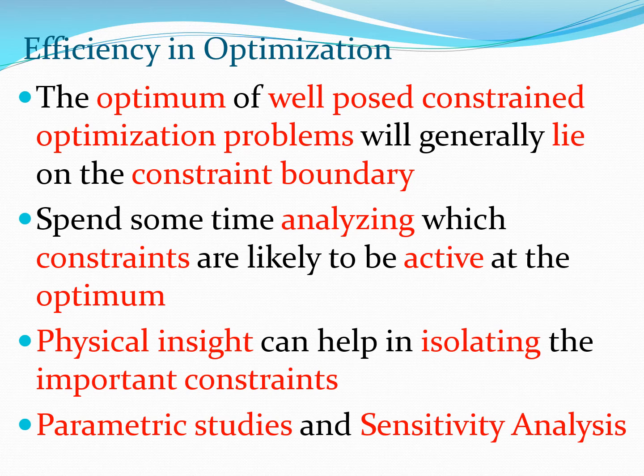So in those cases, you can do parametric studies, or there is a whole field called sensitivity derivative calculations. And these particular parametric studies and sensitivity derivatives will tell you something about which design variables are most important. Now in parametric studies, you essentially vary the value of the different design variables and see how the cost function and the constraints behave when you vary these values. So you could fix one value or a few values and you could move some of the values. So basically parametric study lets you get a picture of the system from various dimensions.